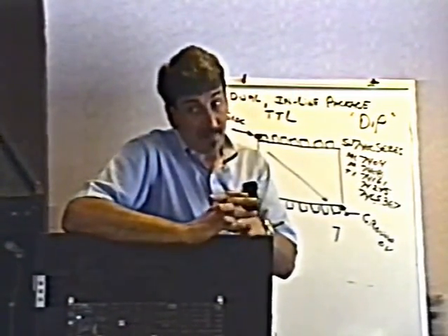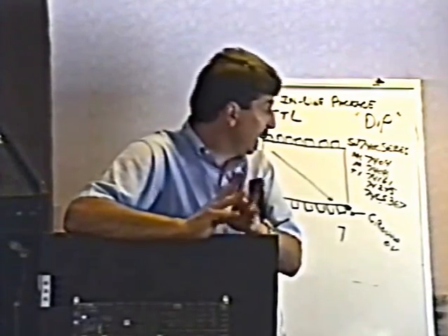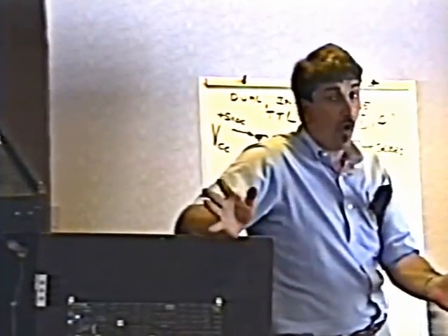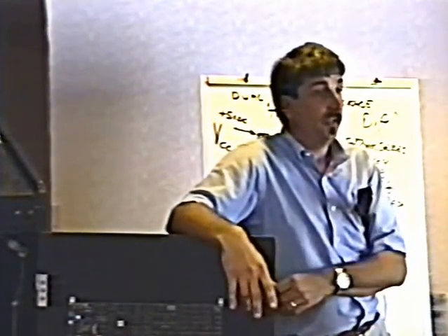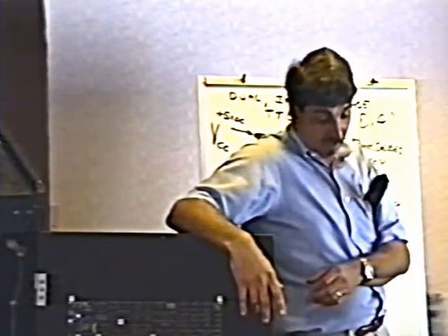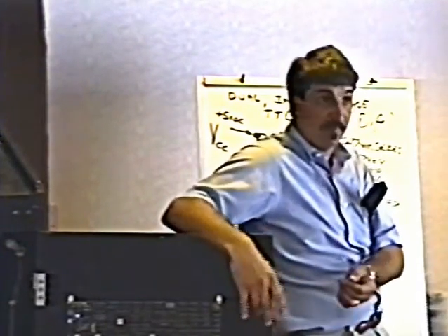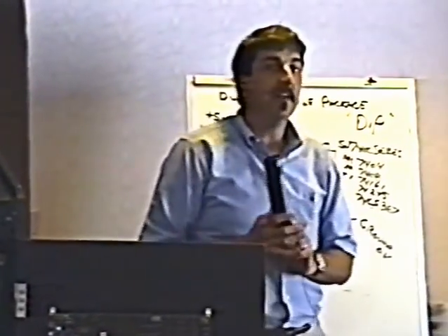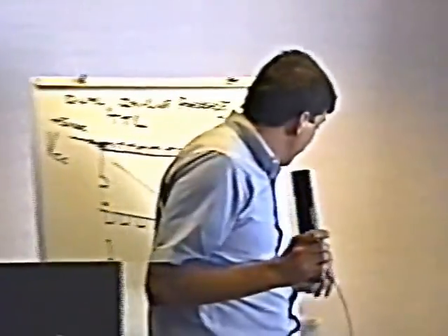Another problem that happens on boards that you can fix real easily is a problem where the game works perfectly okay when it's cold, but when it warms up, it fails. We've all had these kinds of problems. Or it works perfectly okay when it's warm, but it doesn't work when you first plug it in, or something like that. These are thermally intermittent problems, and these are real easy to find.